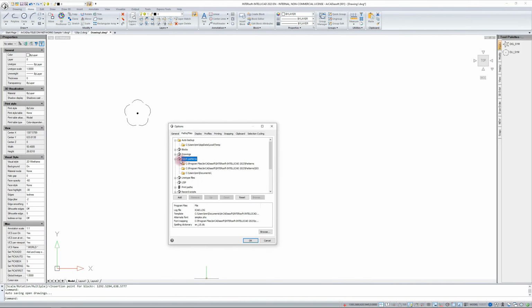If we do not have a font installed on our computer and it was in a document, it will be replaced with another one. If we want to have the same one, then the program will tell us at the very beginning when opening, here in the command area, that some font has been swapped. Then simply install this font and open the file again. And this font will be there.